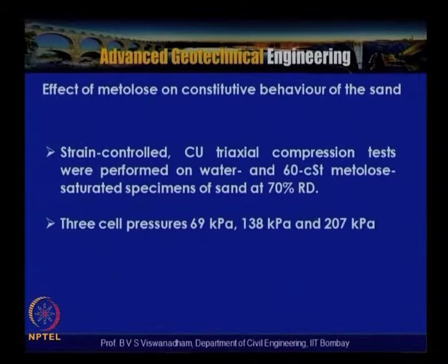So the effect of the metolose on the constitutive behavior of the sand was investigated, and strain controlled CU triaxial compression tests were carried out on water and 60 centistoke metolose saturated specimens of fine sand placed at 70% relative density. Three cell pressures of 69 kilopascals, 138 kilopascals and 207 kilopascals were maintained.